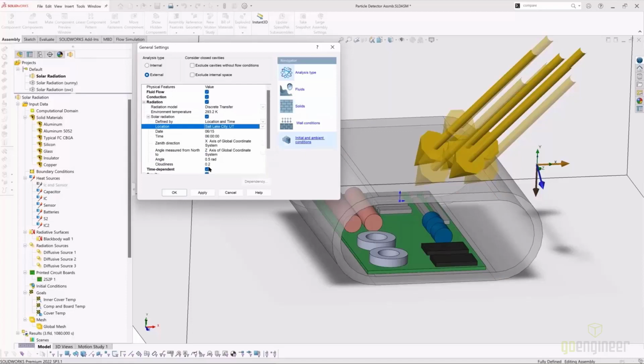And yeah, we can change that with the radians, but I already have this solved, so I'm not going to change anything here. Likewise, we can set an actual time of when this study would be run. So say this is 6 p.m., and we're going to run this until 7 p.m. on a decently sunny day in, what is it, June?